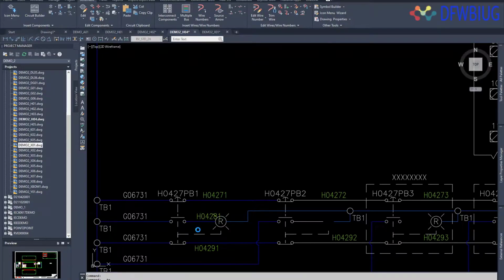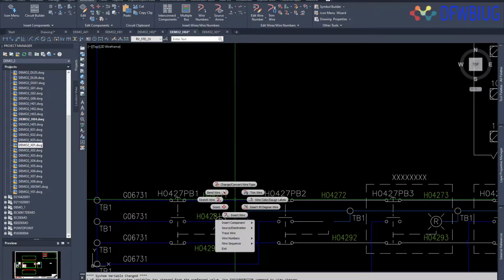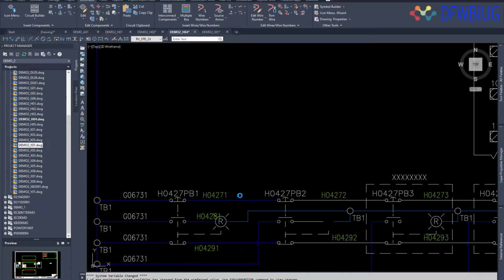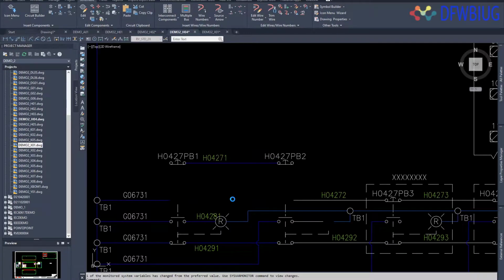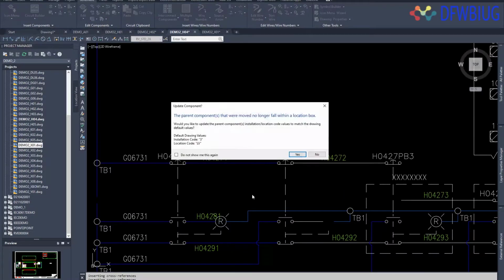Okay. Now, that being said, that wire number is tied to that wire. If I remove that wire intelligence from that wire number, that number goes blank. That number is a floater. It does not apply. If I were to scoot this wire, you will see anything attached to it follows it. Therefore, I do not break my connectivity.